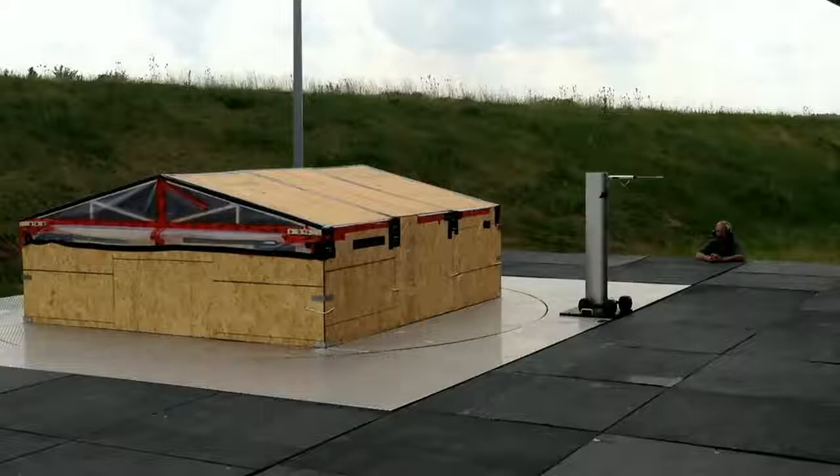For this test, withdrawal of the toenail roof-to-wall connections is isolated as the failure mode, as it is typically the most catastrophic and increasingly common form of wind-induced damage to light frame wood structures. This test specifically assesses the displacement behavior, failure mechanism, and failure wind speed of the unretrofitted structure.